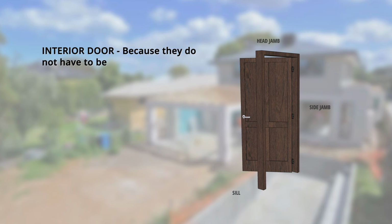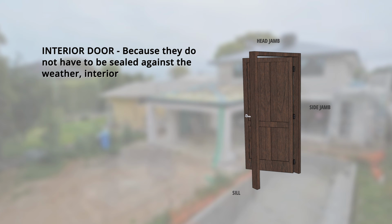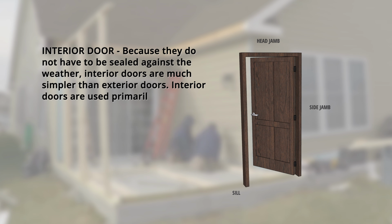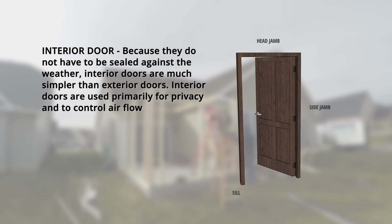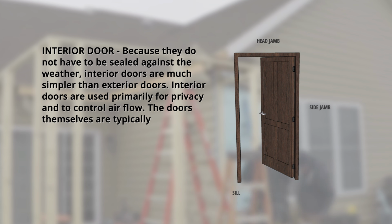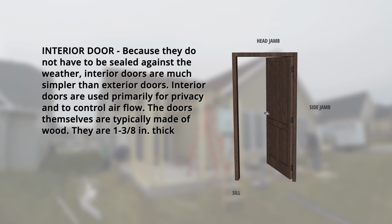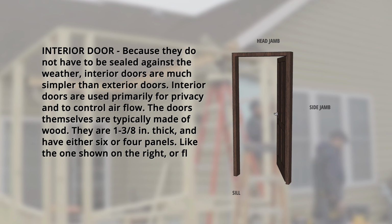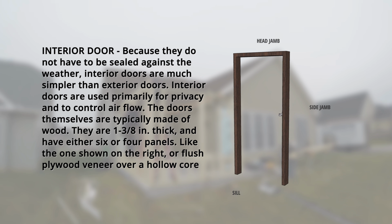Doors. Interior door. Because they do not have to be sealed against the weather, interior doors are much simpler than exterior doors. Interior doors are used primarily for privacy and to control airflow. The doors themselves are typically made of wood. They are 1 3/8 inch thick and have either 6 or 4 panels, like the one shown on the right, or flush plywood veneer over a hollow core or solid core.